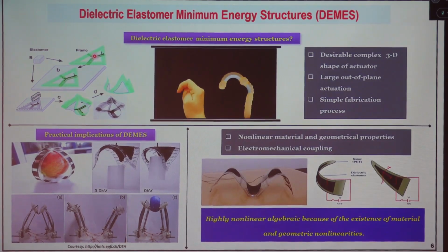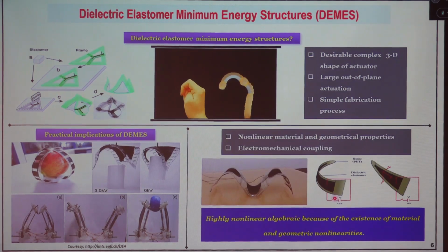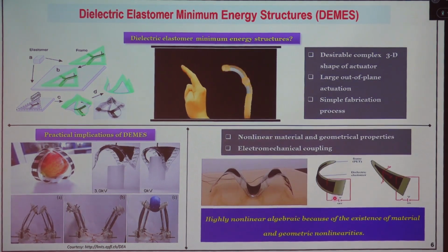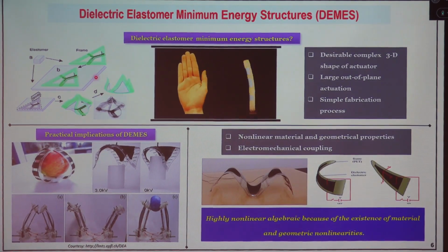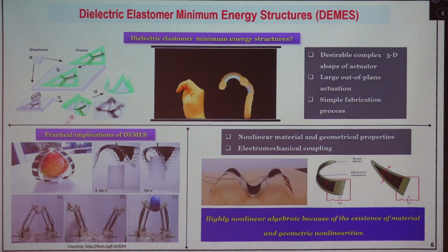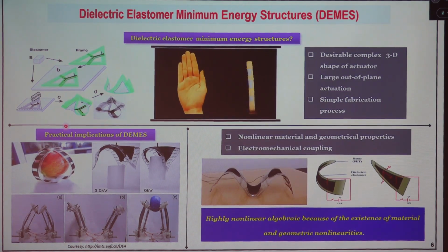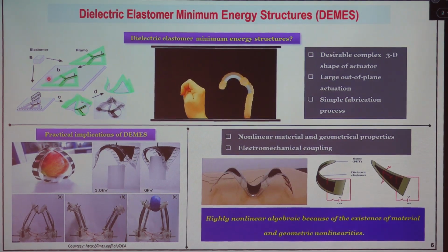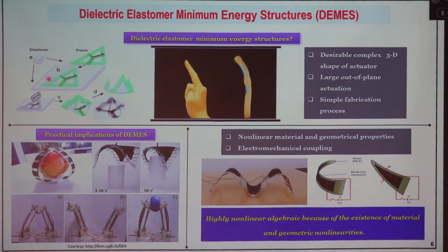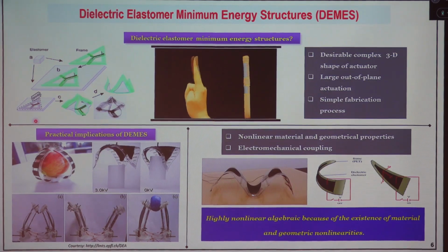For example, I want to develop a simple bending actuator. I take this compliant frame, cut it, and make some hollow section at the center position. Then, on that pre-stretching mechanism, we put that compliant frame. This is a pre-stretched membrane, already pre-stretched in the stretching mechanism. We apply the compliant frame over that. At the top and the bottom, where we have the hollow portion, we can put the carbon grease. Then you can cut it with the help of a razor blade.